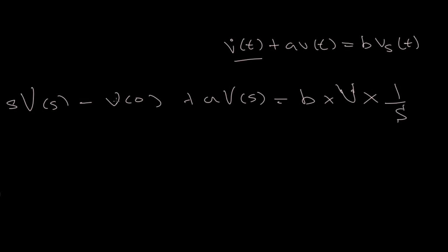V s is the Laplace of the capacitor voltage, v t. v0 is the initial condition of the capacitor, which could be some initial voltage the capacitor had. V is the supply voltage, and the step input helps to show that it's a consistent supply input. Yeah, that's it.